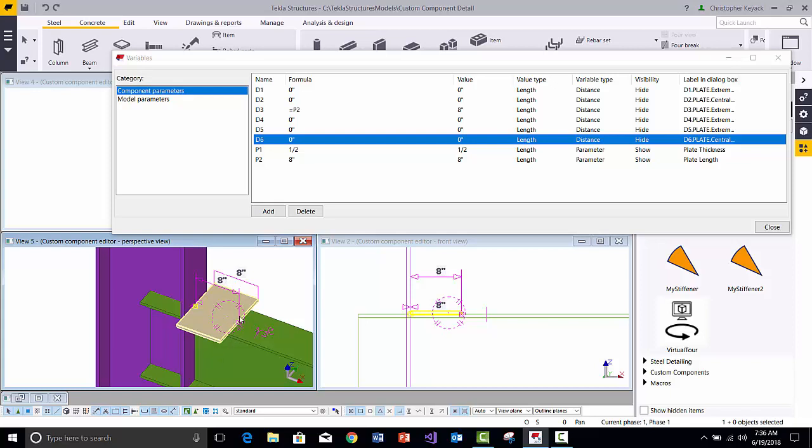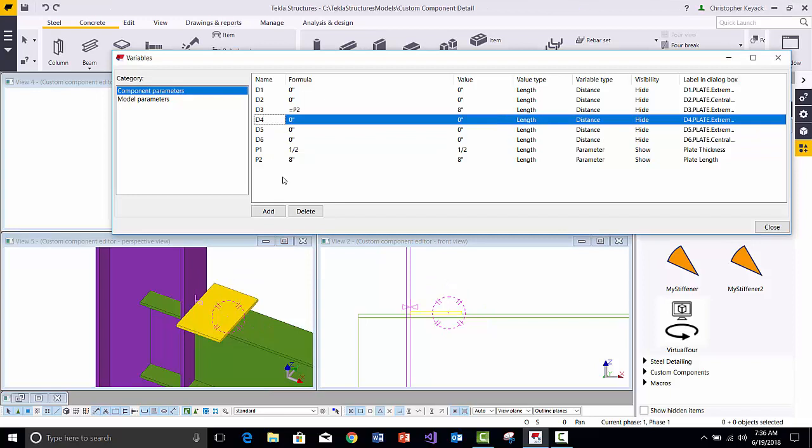If you mess up your bindings early on parts here and you start adding bolts and certain things like that, you might get things that you don't expect happening. Like if you forgot one of your bindings and then you modify some parameters, things might flip out in your component and you don't know why. So it's always a good habit that when you do each of your bindings, do one point at a time and make sure that you've bound them all in the direction that you want.